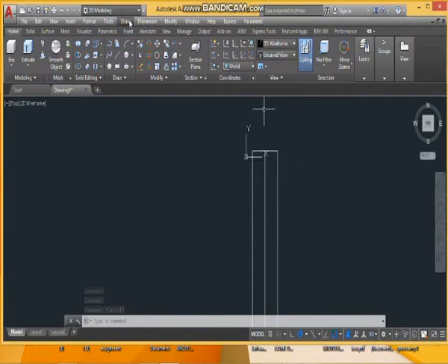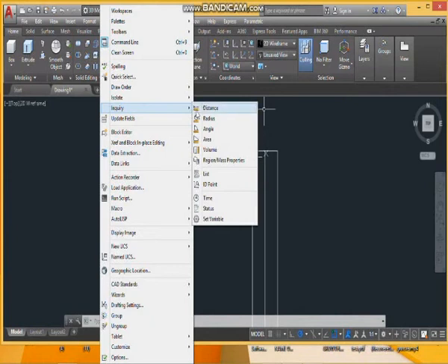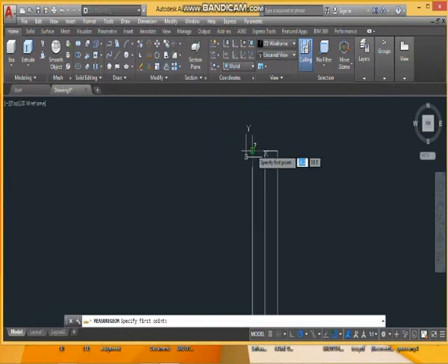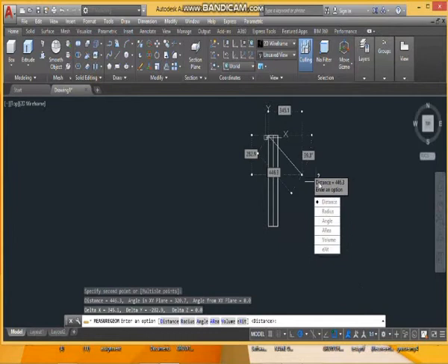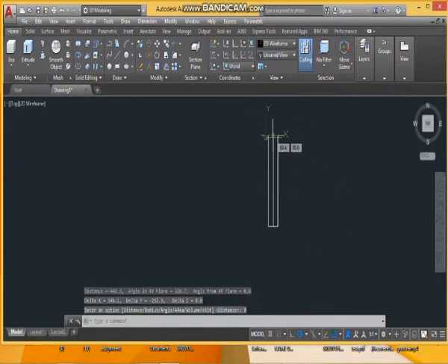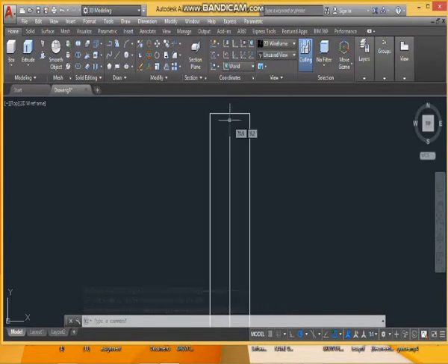Alright, now let's go back to measure and be very sure that if the width is 100 millimeters, the half of it should be 50. Our length is also measured to be very sure of what we are doing, because sometimes in AutoCAD you give a command and the output may not be exactly what you desired, so you might have to always measure it.